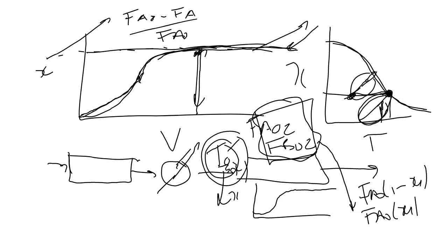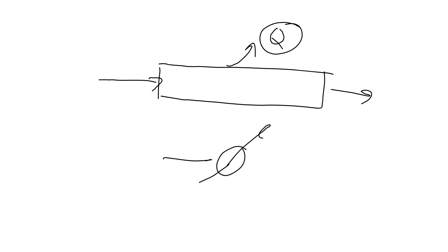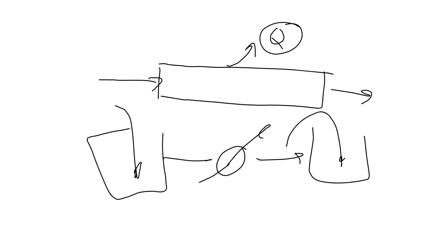I am not going to expect that of you, those who ask the question. So I am definitely not going to change this question to say optimize volumes of two PFRs in series, because you simply will not build the PFRs like that. What we're going to explore after the semester test is that it is much better to have a single non-adiabatic PFR. In a CSTR you want that jump in temperature, jumping temperature, boom, to the maximum. Because in a PFR you don't have that. You have this gradual temperature profile.